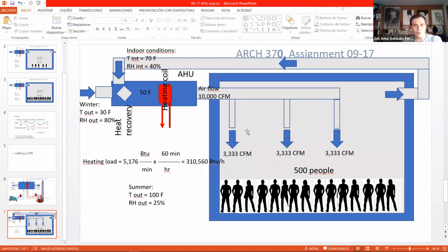So that's why we need to use different diffusers. It doesn't affect the heat power or the heating loads, but it will affect other things. Okay, so we will end up calculating those ducts and we will select as many diffusers as we need.